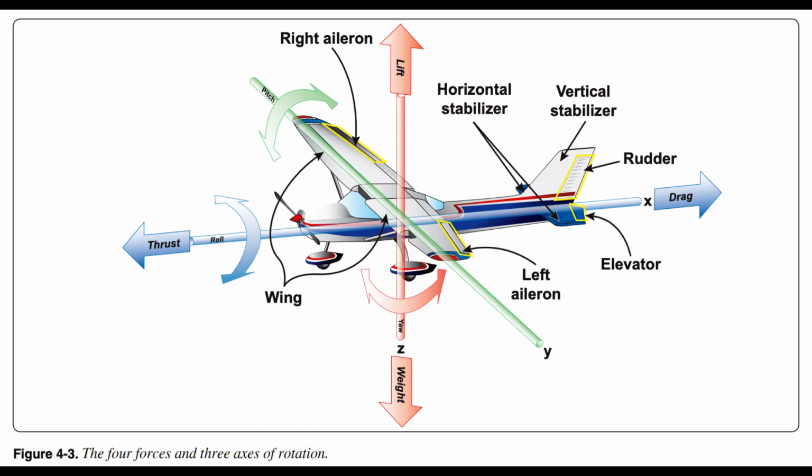form drag is reduced. Total lift must overcome the total weight of the aircraft, which is comprised of the actual weight and the tail-down force used to control the aircraft's pitch attitude. Thrust must overcome total drag in order to provide forward speed with which to produce lift. Understanding the aircraft's relationship between these elements and the environment provides proper interpretation of the aircraft's instruments.